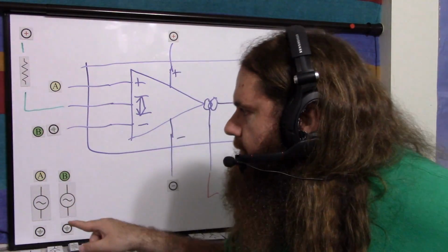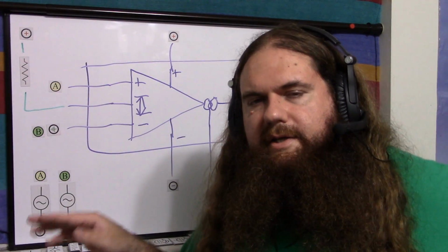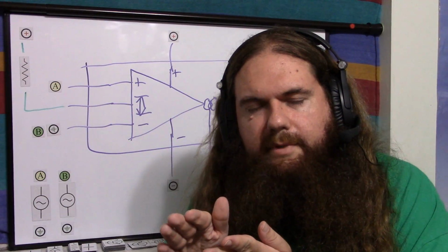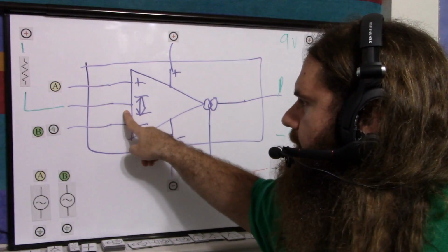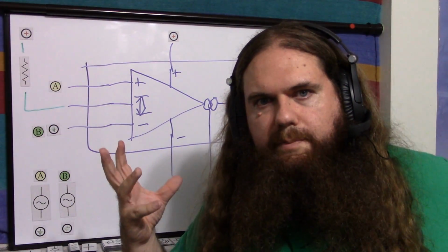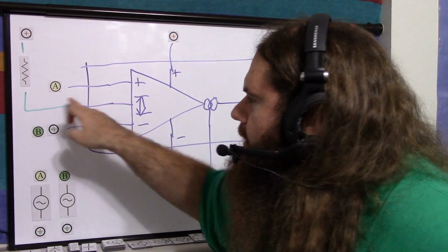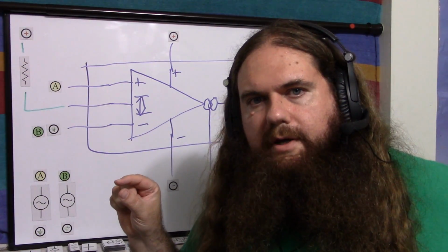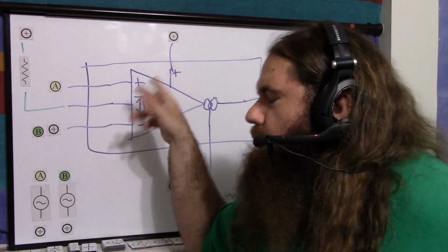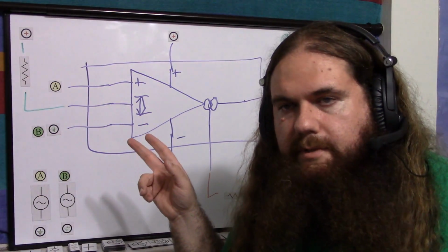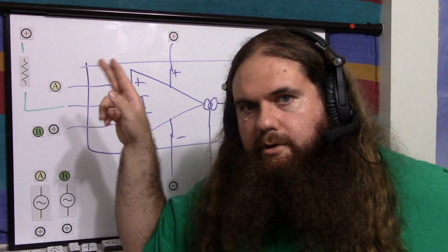You have to do that yourself with the voltage divider, so make sure A minus B or A minus ground is never higher than however many millivolts you decide. Use a voltage divider on A or A and B. Your linearizing diode input can be left open if you don't care about noise or distortion. If you do, then look on your datasheet and see what the datasheet recommends. Mine recommends, I'm using the TI datasheet, Texas Instruments, and 1 to 1.3 milliamps seems to be right. So your positive voltage, that many milliamps, gives you this resistor, hook it up and leave it.